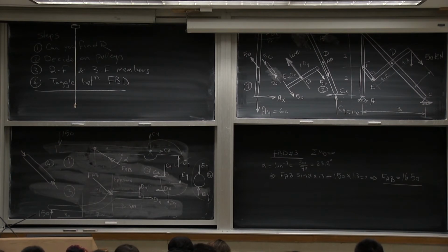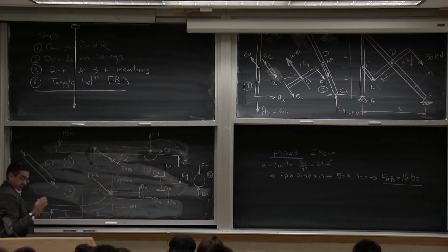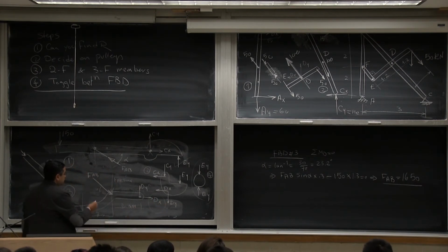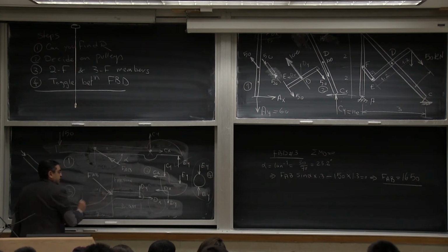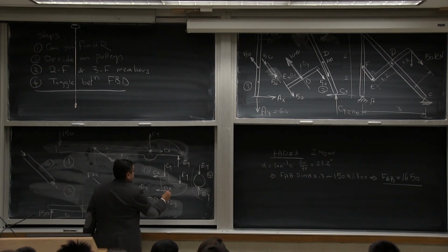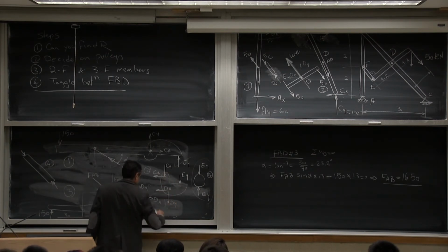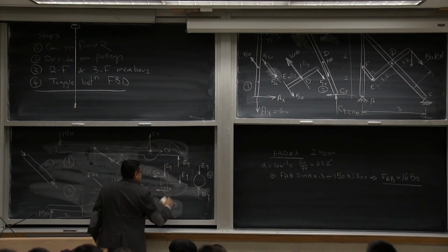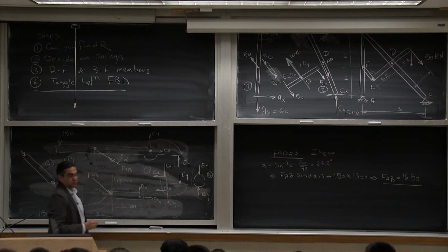Is there an easier solution? Yes. Can you just find the y coordinate at E so it cancels out, so you don't even need the entire result? Okay, so what he's saying, I think, is if you find DX here, which is basically sigma FX, and you come here and take the moment around C, this is the same line. So you can immediately find EY.